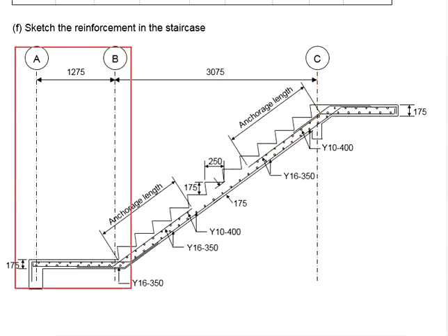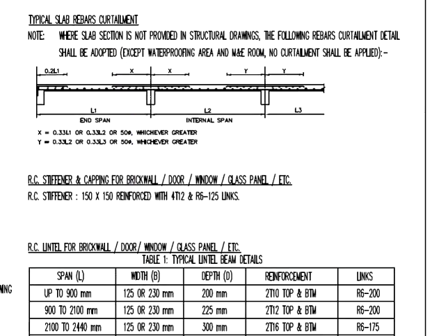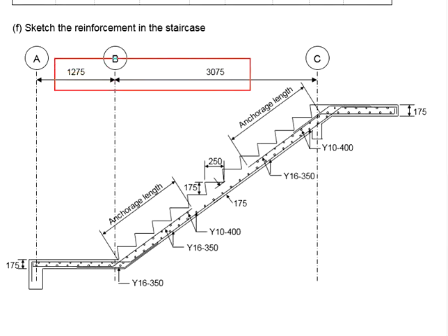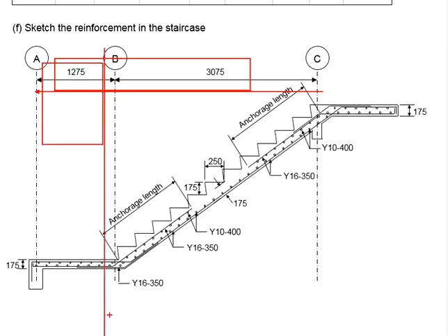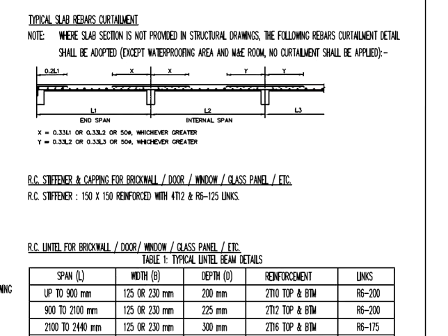You can do the similar at the end span here, which is defined by 0.2 of the span here. That means you are quantifying the 20% of this entire span. Identify where that 20% is, draw a straight line, and then this shall indicate where the anchorage length should stop. Just that if you choose to adopt the principles of this, it is the 20% of the end span, the 1/3 of both spans, and at least 50 times the bar diameter.